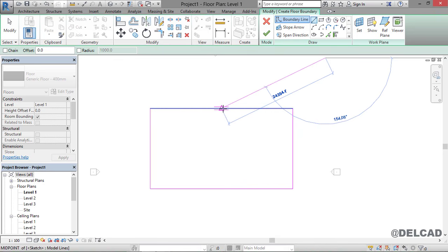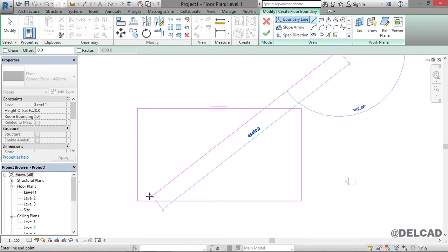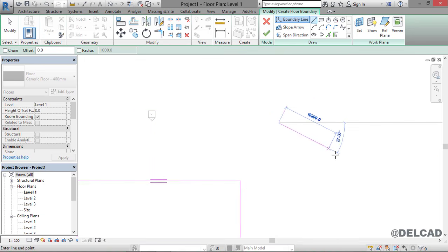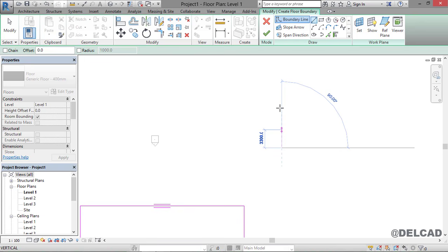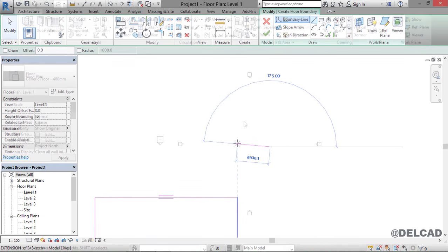We can also target the midpoint, so that is indicated with a rectangle, so this is the midpoint. We can also target the angles, so you have angles here at different angles. You can also target the extension lines when you have it completely vertical or when you have it horizontal. So with the help of this dashed line, you can also get a good drawing when you're using Autodesk Revit. All this is achieved with the use of the snap settings, and that is why it is important to also make sure that that is set before you start your project or your drawing in Autodesk Revit.